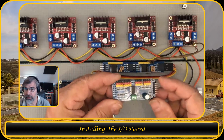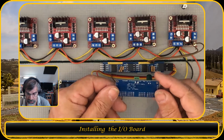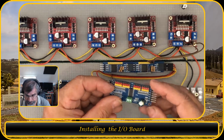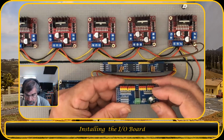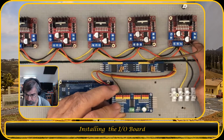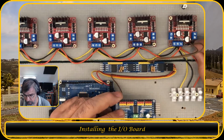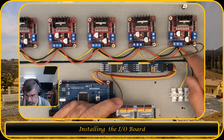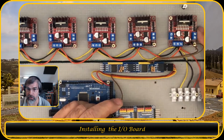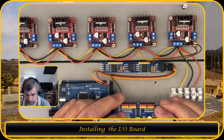Then I have this controller. This is a servo driver controller, the PCA9685, and the yellow pin is the pulse width modulation pin, which is going to be connected, instead of the jumpers which are placed here, to the enable pin. If I don't remove the enable pin and I put a 1 or a 0 on these two pins, then just the 12 volt will go out on this side or that side, depending on which one is connected.